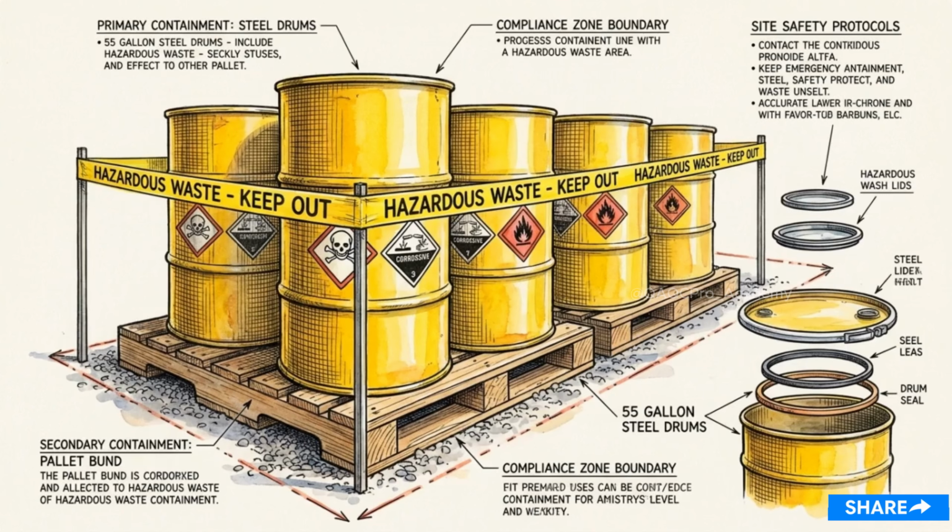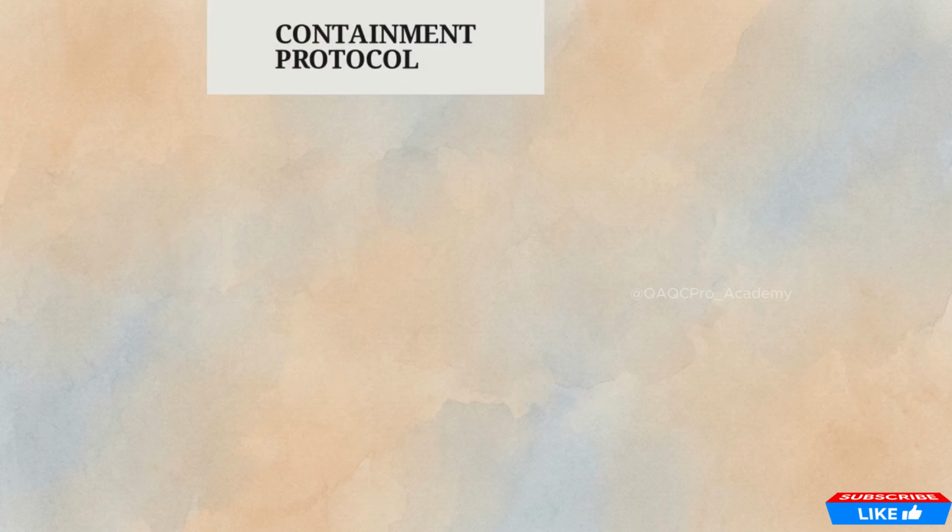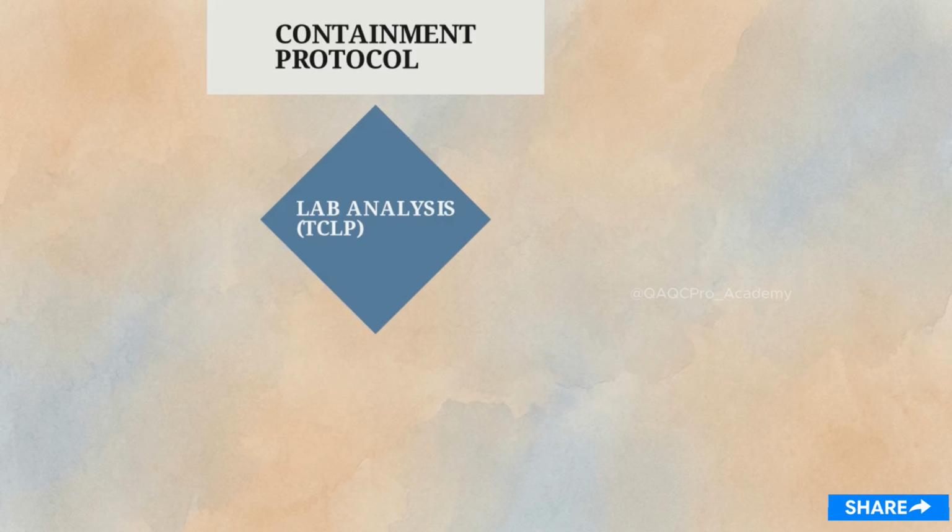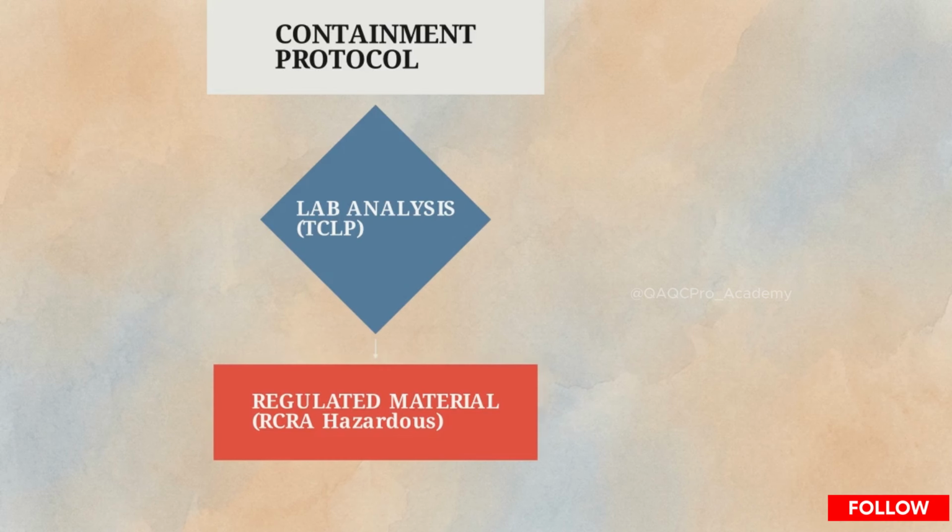Factor 6 covers environmental and disposal constraints, and this is where the heaviest liabilities live, especially when dealing with lead paint or contaminated field substrates. Removing hazardous coatings triggers mandatory TCLP testing. If spent media leaches heavy metals above EPA thresholds, every ounce becomes hazardous waste.